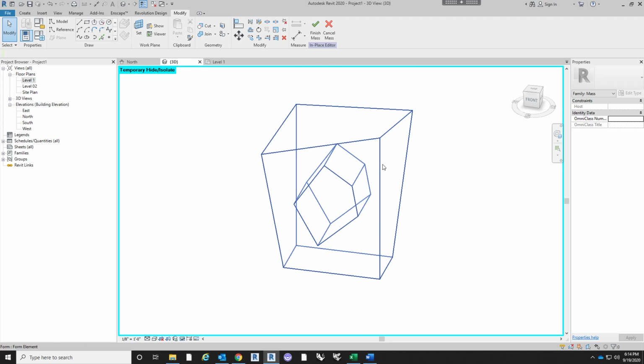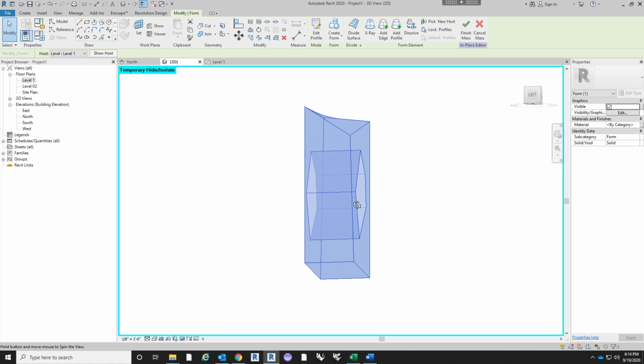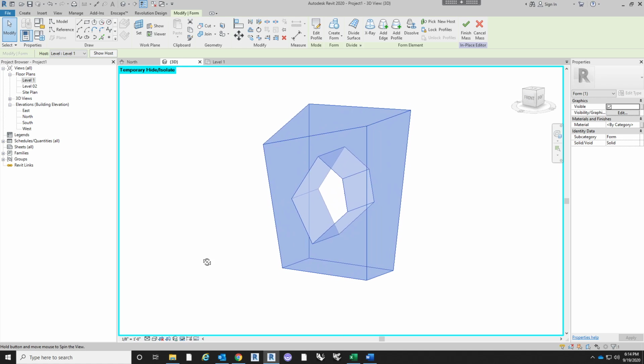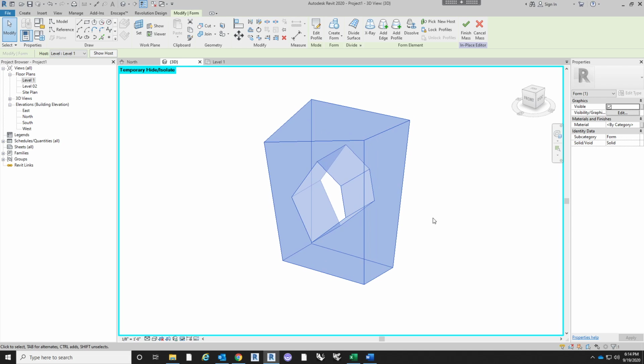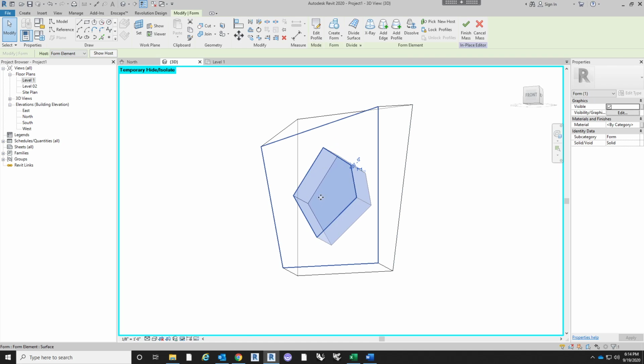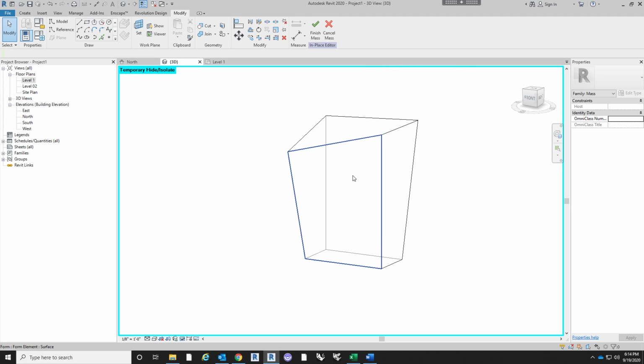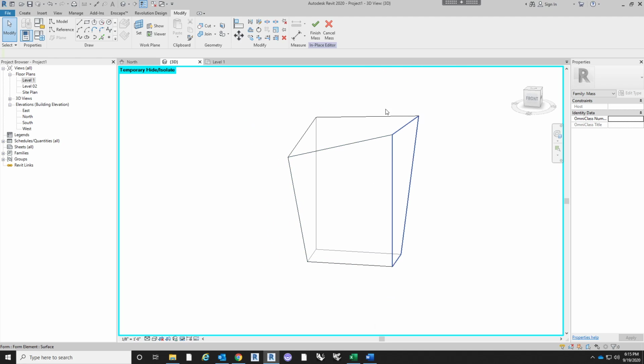And it has cut through that element with this element. The problem is that you created it with another solid geometry. So that solid geometry stays in there, and you can delete it. But then all the geometry that the bigger geometry was referencing to cut through it is now gone.